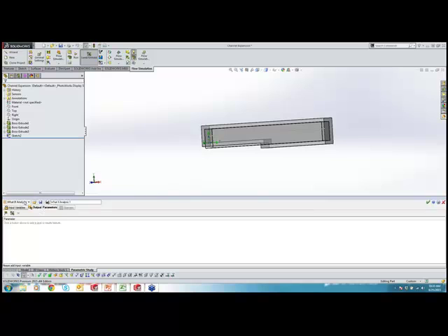If you do it this way with the optimization or the what-if, especially the what-if, it'll do the study, and you can say, I want you to solve for the piston in this position to this position with this many steps in between, and just give me the result, and it'll make that chart for you. So if you know right where that fine line is, you can set it to run the what-if right in that area. Okay, yeah, that's certainly what I was looking for.